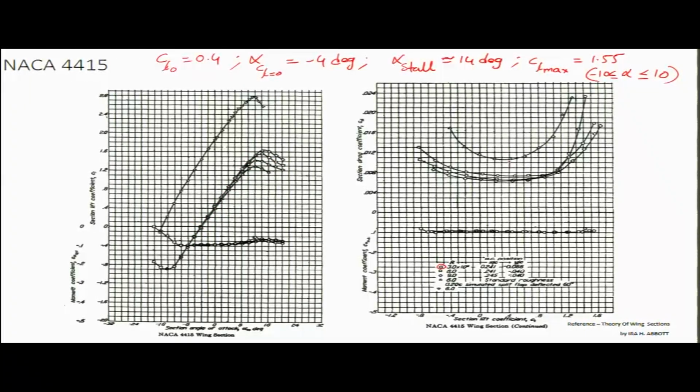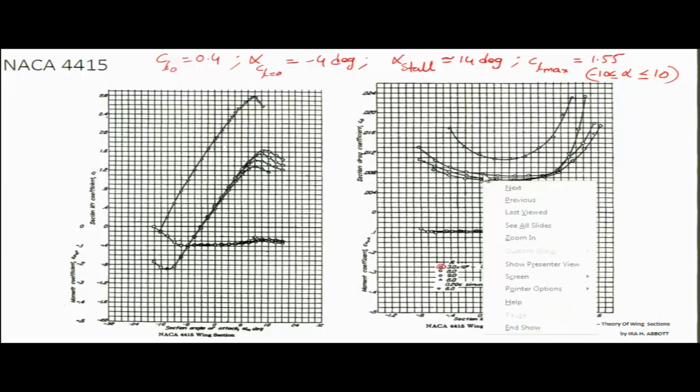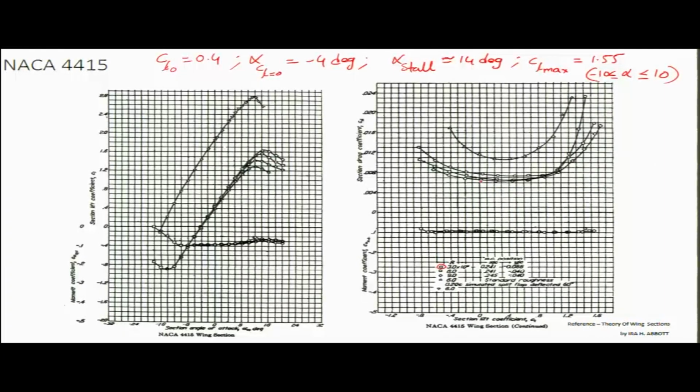And the corresponding CD value for this is CD naught. If you want to find CD naught, the CL is 0 at this particular location. So this is approximately, for 3 million Reynolds number, 0.0079 or 0.008, that is, CD naught is approximately 0.008 for an airfoil, right.